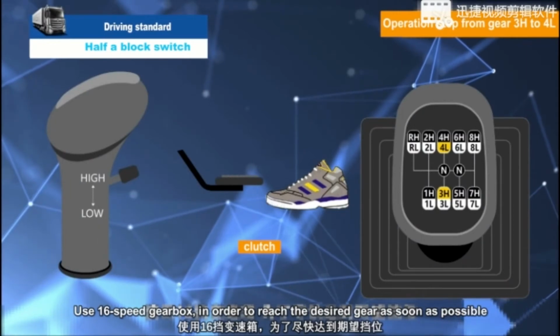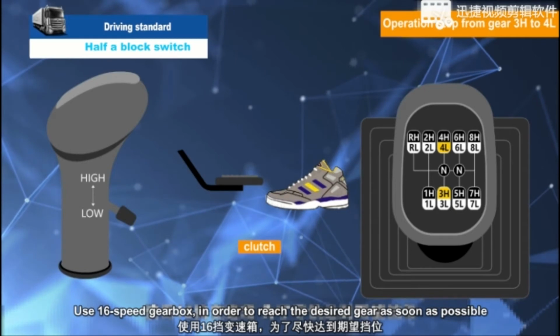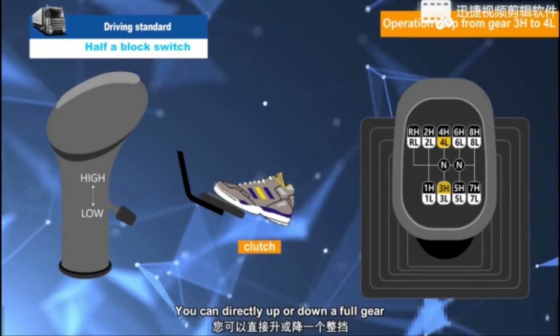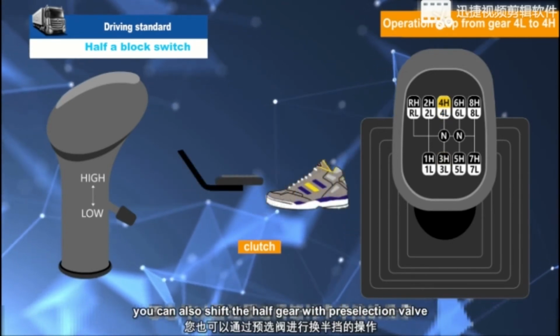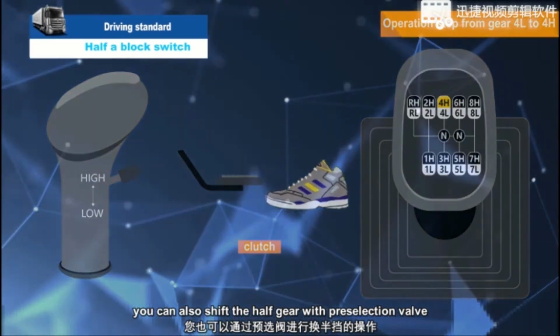Use the 16-speed gearbox in order to reach the desired gear as soon as possible. You can directly shift up or down a full gear. When it is required to accurately control the gear, you can also shift the half gear with the pre-selection valve.